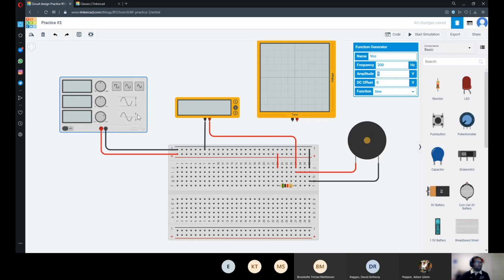As we can see in the figure on the left, the amplitude is measured from the top of the signal to the bottom. That's what's called the amplitude peak to peak. And we can also change the frequency of the signal that we're creating. So these are going to be signals that are periodic, so they're going to repeat over time. So that's where we can change the frequency.